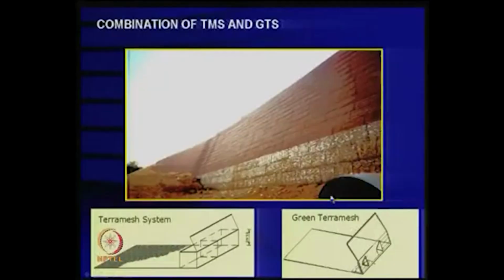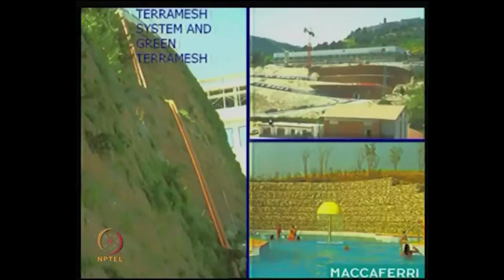In fact, what I saw in a particular RE wall, RE slope in another place called Vijayawada, was that they could not estimate the deformations of the slopes properly. That was a big issue. Now it is somewhat stable, but it has really been a problem in reinforced soil slopes, because the height is 42 meters, which is not a small height, and it is also on a curvature. There are many design issues, and this is another example that one can have here.